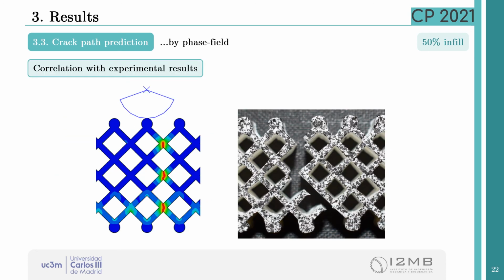Comparing the results we obtained, we can notice that the numerical crack does not correlate with the experimental one. The numerical models have no manufacturing defects. The grid pattern is a perfect repetitive geometry with no pores or design alterations. By contrast, the printed specimens have critical imperfections that could advance fracture growth and also have a strong influence to lead the crack path, like in this case.